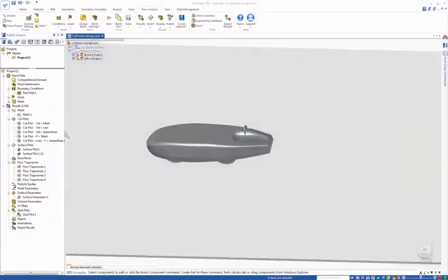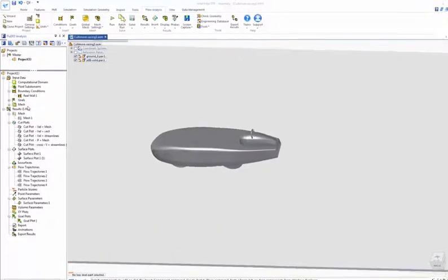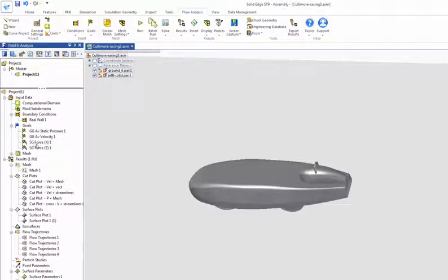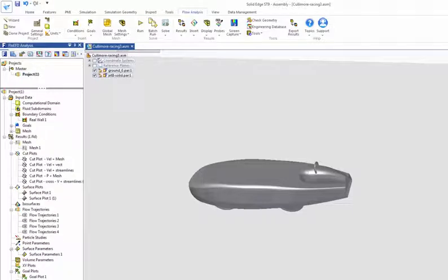So far, we have shown various ways of visualizing the flow, but let's say that the engineer would like to extract some quantitative values. We had set up a goal prior to the run for the overall drag force acting on the car, so this information could be accessed easily now from the goal plots branch of the results tree.